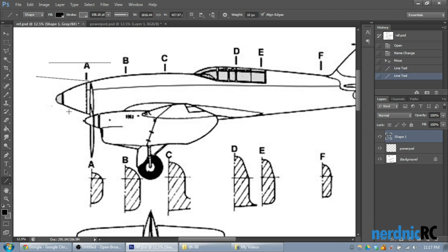One of the other things I'll be doing a lot with the line tool is holding down the shift key. You can get a nice straight line if you hold down shift and then click and drag, and if you move your cursor around, it'll jump to 90, 45, so it makes a nice straight line. If you do not hold shift, then it's free, whatever you want, and in the little info box it'll tell you what degree you are, what the length is in centimeters. So shift is going to be something we use a lot.